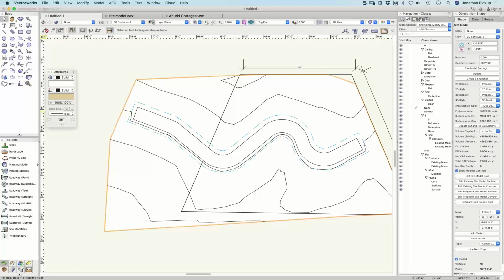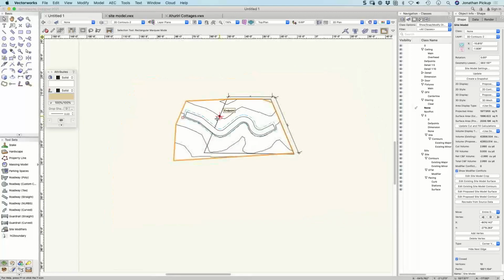So let's start going through the questions. I've done the road, laying the roadway down on top, I think. You already have the contour lines and are creating just the points. So if you're creating it from just points, it's basically the same. You just put stake objects on top of all the contours. So if you import it and it's 2D only, you put stake objects down for all of those points.